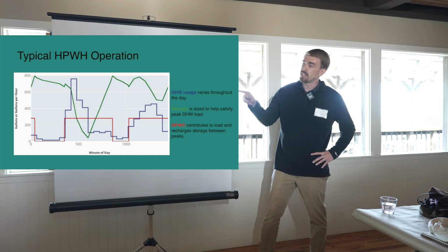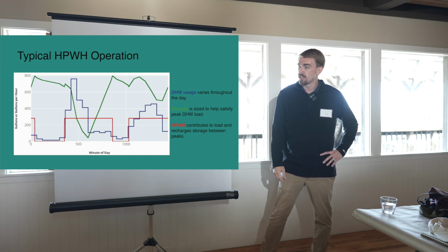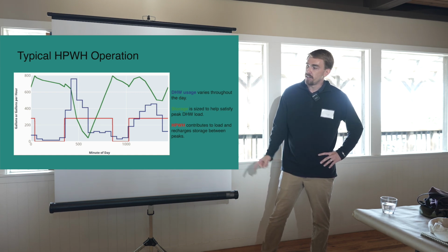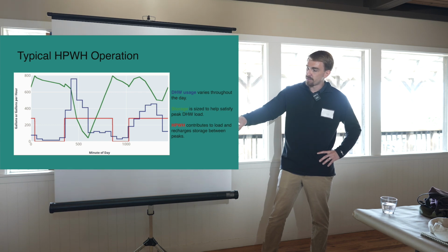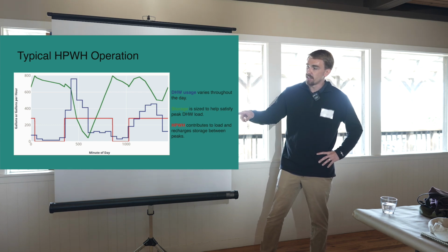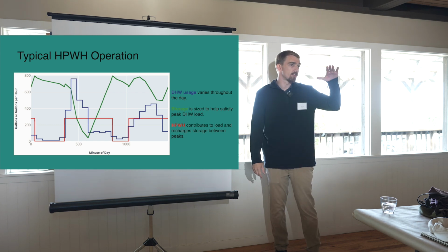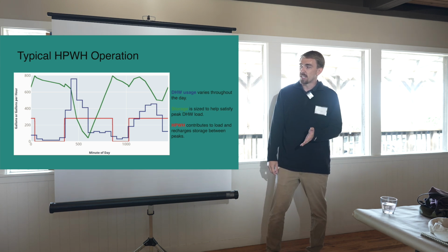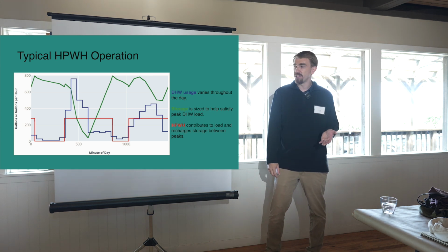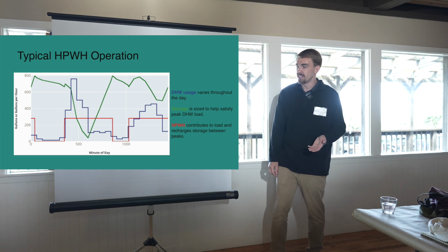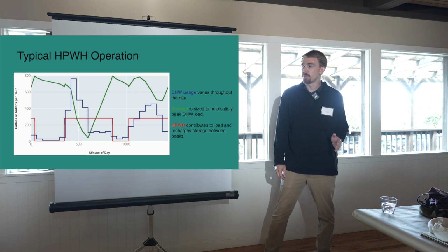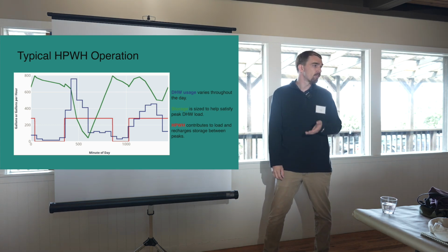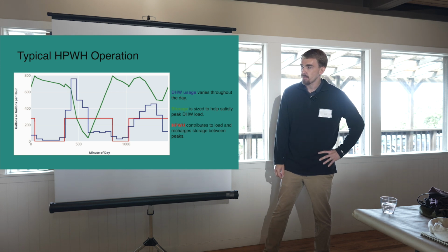So how that looks throughout the day is the storage starts fully charged. We have our morning peak. You can see the storage just drops off significantly during that peak, and the heat pump turns on as soon as that storage volume starts to drop. Right, and then that peak subsides, hopefully before we're completely out of storage if we've sized the system right. And then the heat pump will slowly recharge that storage before the next peak period.